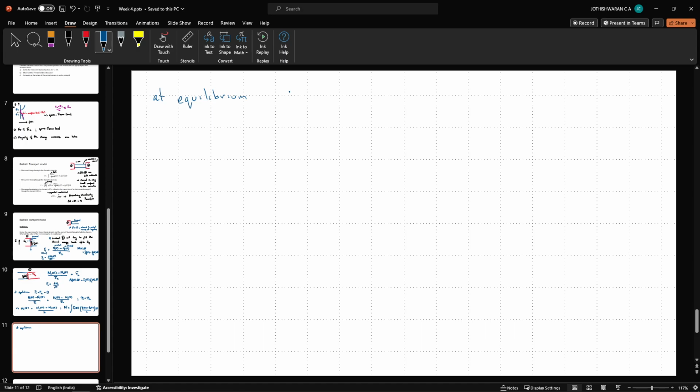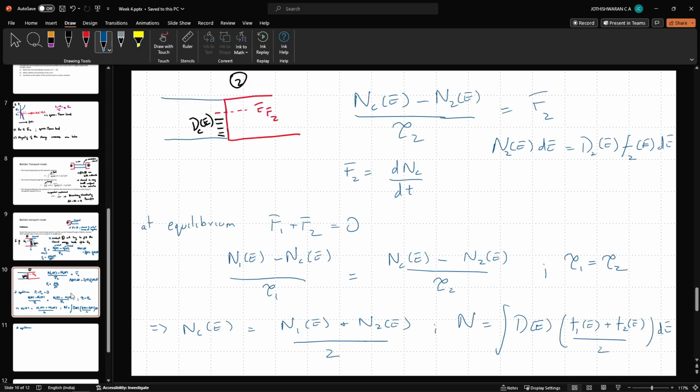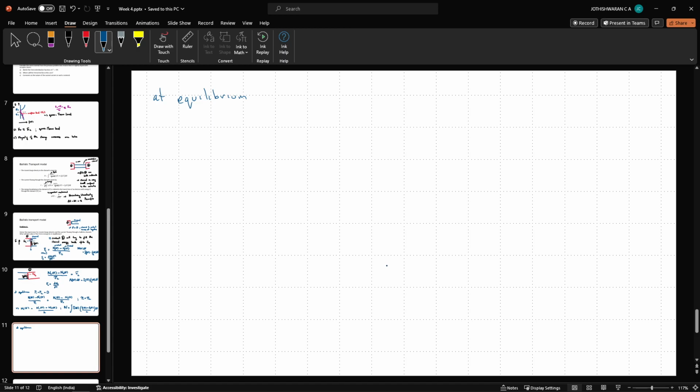So these two are both competing. What we have found is the equilibrium condition where some electrons are being stored in the channel and the rest are just moving. Up to what point are these getting stored? We can see in a straightforward fashion that it will usually be half of the electrons being sent in by contact 1, assuming EF1.